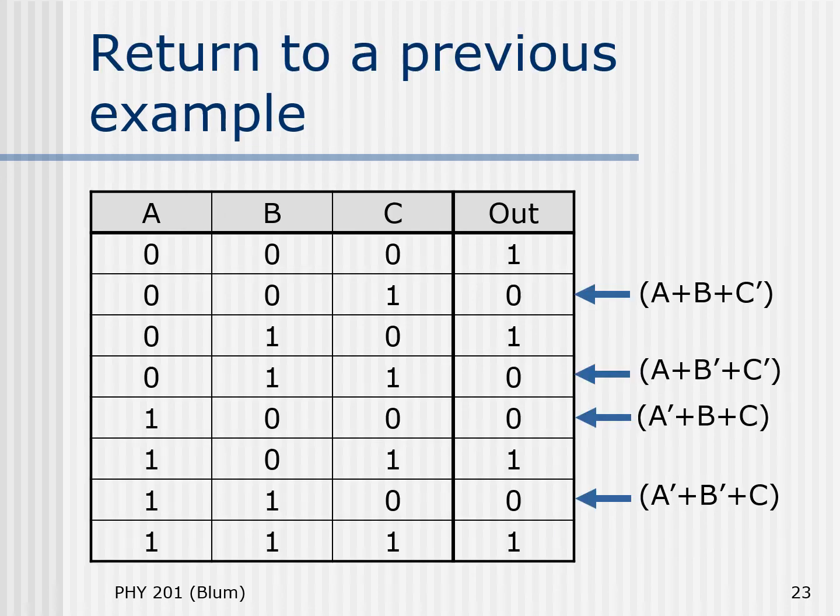So to emphasize that we could take either approach, sum of products or product of sums, to any of our truth tables, we return to a previous example. And now we're going to take the product of sums approach. So we will focus on the 0 outputs and write their expressions. So that expression for the first blue arrowed row is A plus B plus C prime.